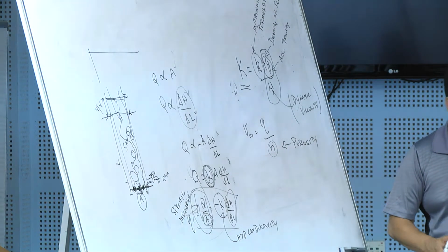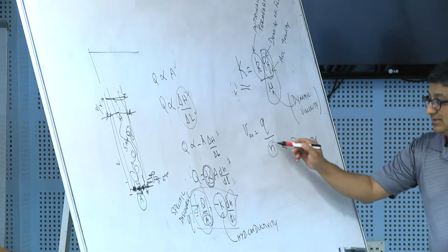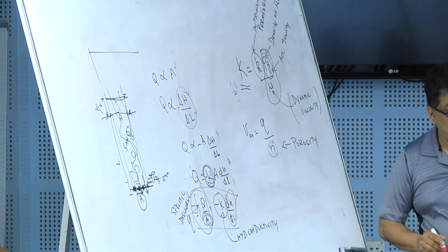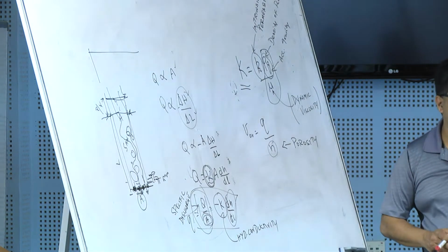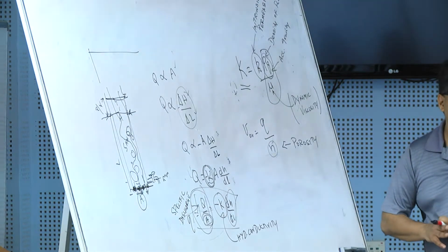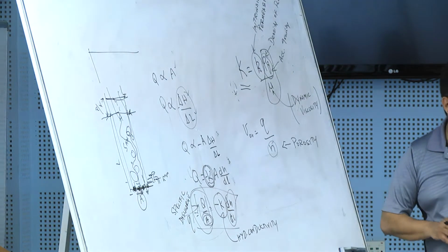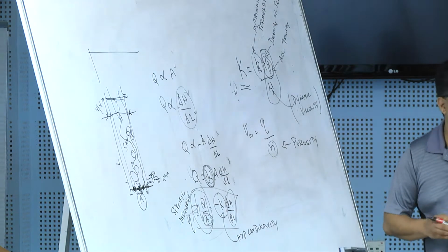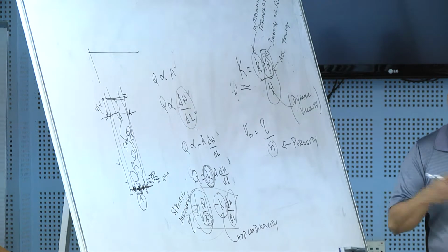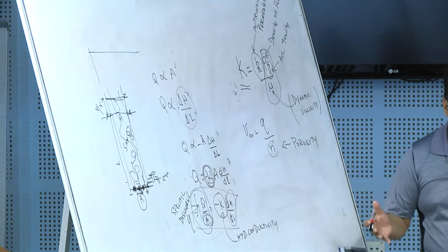So the velocity is, we have to divide this by porosity. Turns out in open channels or in pipe flows, where we first learn Q over A is equal to V, our porosity is equal to what? Porosity is equal to 1 because the void space is exactly the same as my total volume.